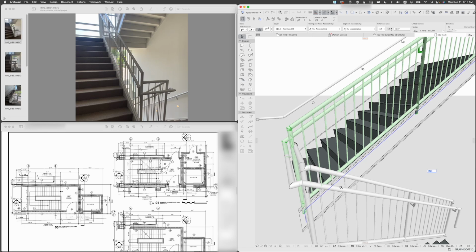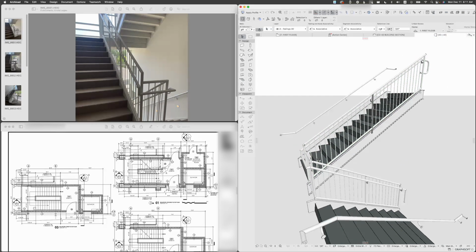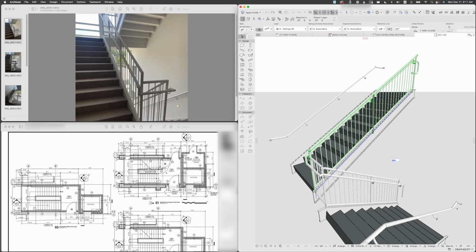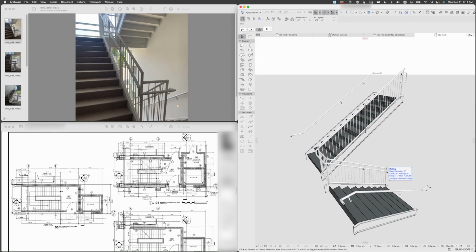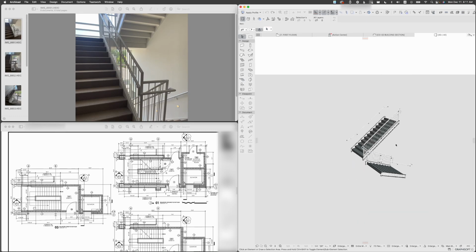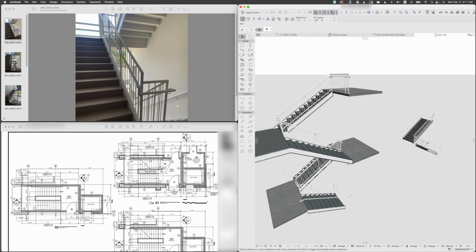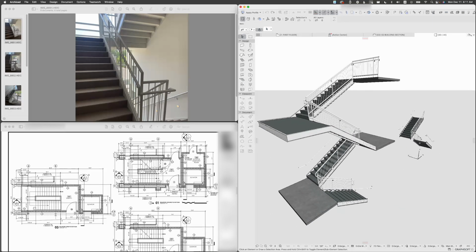You have to enter proper numbers to calculate this. You have to draw a section, so I'm not sure if it's really the best method, because there's actually a method of building a railing based on both stairs, like one element. It will consist of 3 segments, similar to what I did on my other stairs here.